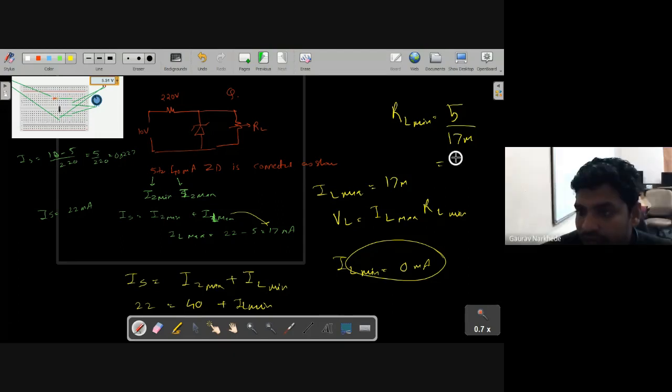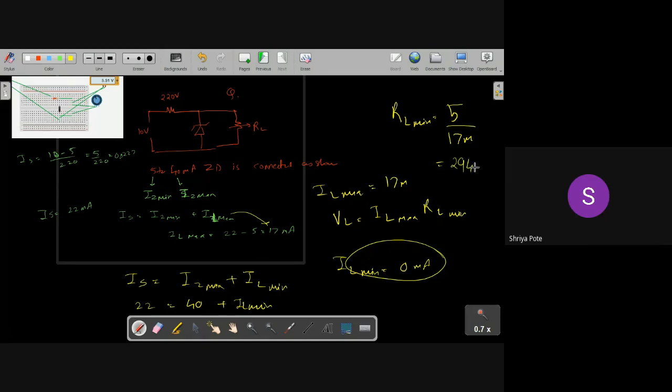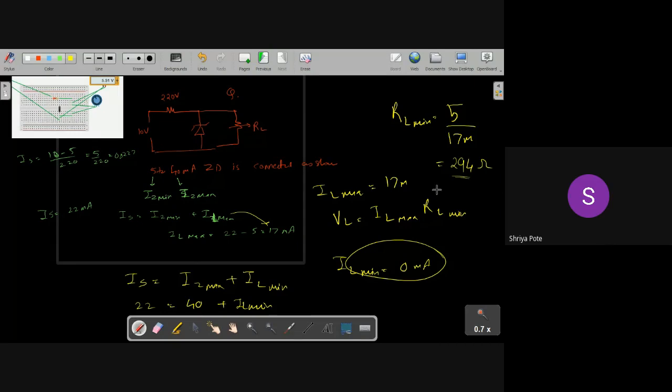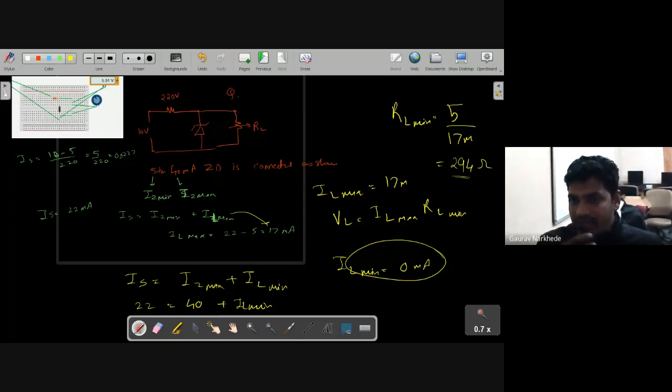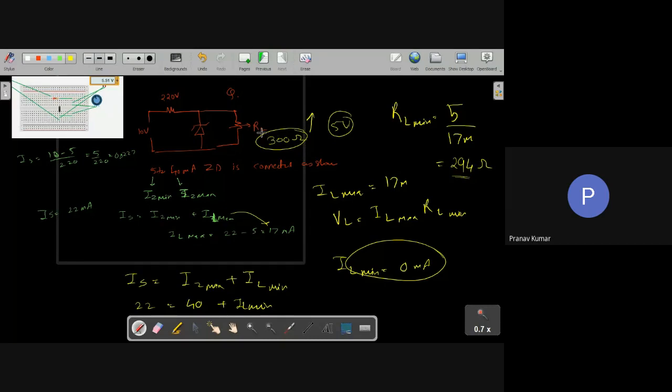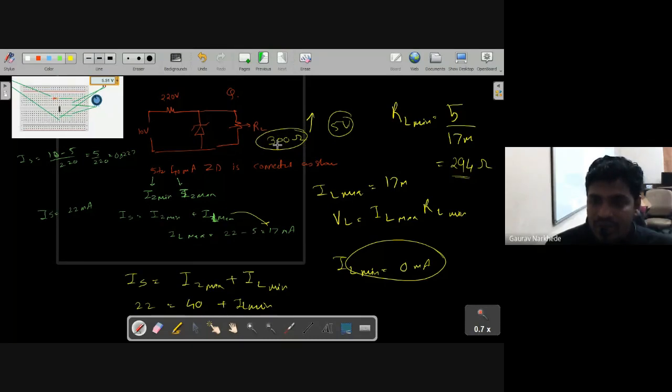और कुछ बोलिए आगे. 294 ohms. ऐसा बोल दूं मैं इसको? Yes, sir. ओके, मतलब इसका मतलब ये है कि मिनिमम रेजिस्टेंस शुड बी 294 ohms. मतलब ये 300 ohms बोल देता हूं मैं, राइट? इसके ऊपर ही आपको आउटपुट 5 वोल्ट्स कांस्टेंट मिलेगा. इसके नीचे अगर रेजिस्टेंस जाएगा तो आपको आउटपुट 5 वोल्ट्स कांस्टेंट नहीं मिलेगा. करेक्ट? Yes, sir. So range of RL, it should be greater than 300 ohms, right?